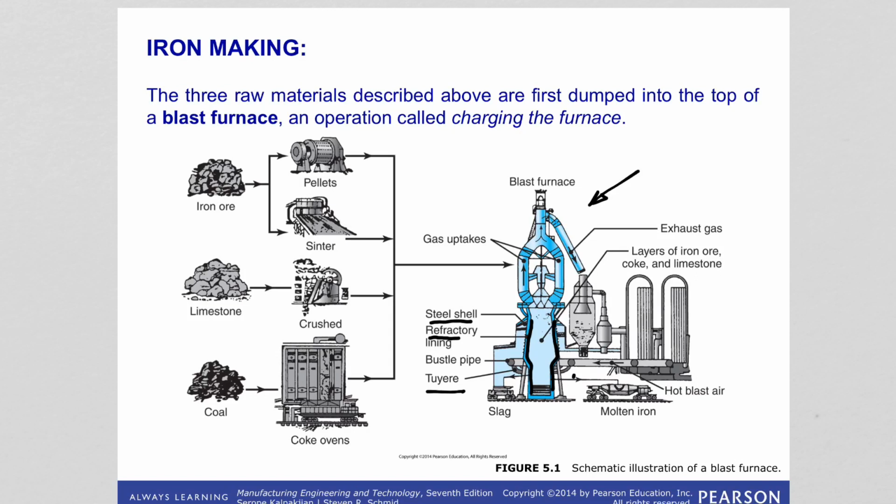Okay, so several reactions take place, but what is the most important and basic reaction happening? It is the oxygen combining with the carbon and producing carbon monoxide, which, as I described, reduces iron oxide to iron. That's the main reaction taking place. So preheating the air is necessary because even the coke, which is the fuel here, might not provide sufficiently high temperatures for the reactions to take place.